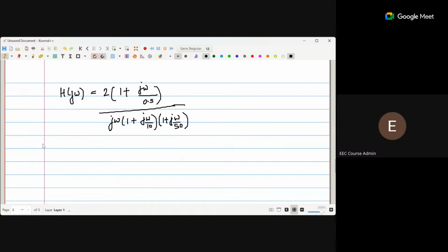So now you have 1 zero and 3 poles. Okay, so z1, these zeros and poles are the corner frequencies actually. So accordingly, where it happens, 0.5. So till 0.5, it will be 0 dB. And after that, 1 zero introduces a slope of plus 20 dB per decade. So that will be going like this. This will be corresponding to this zero, z1, which is corresponding to this term.